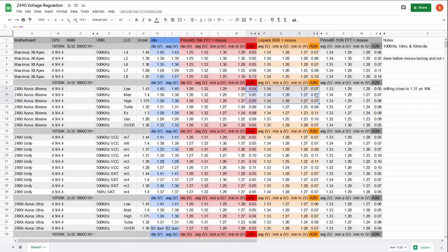But there's also a chance that the reason I'm not measuring any difference is because we're just hitting the limits of what the CPU socket is able to do. We need more power pins, basically. Because if you put all the capacitors on the other side of the socket, a lot of the switching noise from the CPU isn't necessarily going to get all the way out of the CPU and to the CPU socket. Which might explain why MSI is doing so well with a CPU socket that looks so empty. Actually, it is empty. There's barely any capacitors on the back.